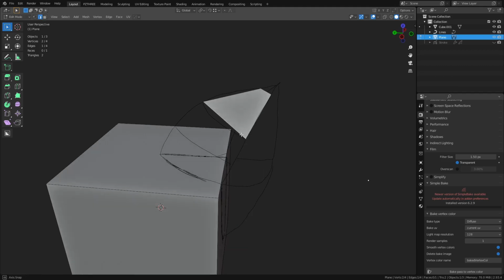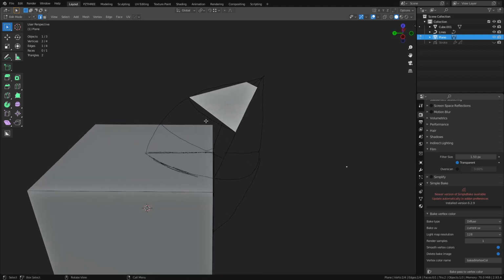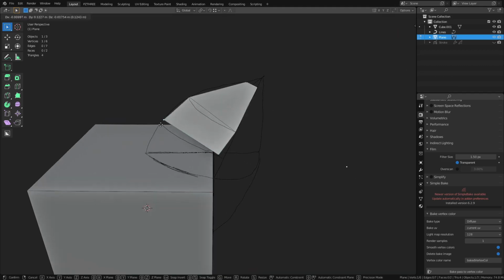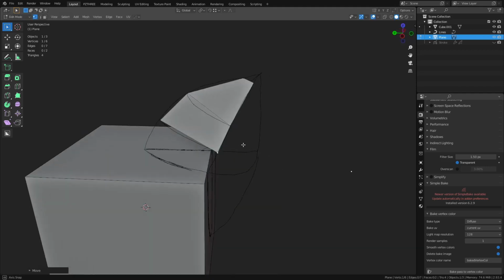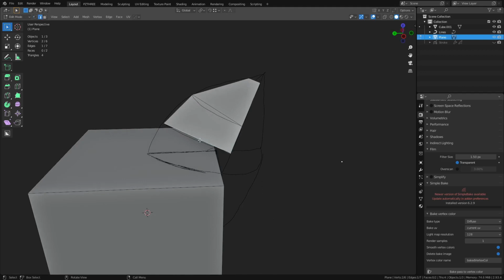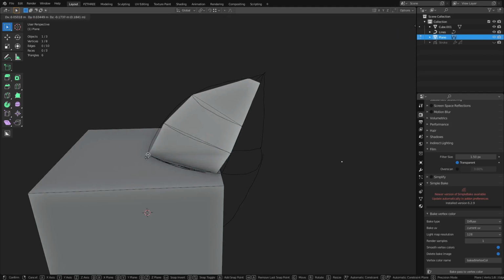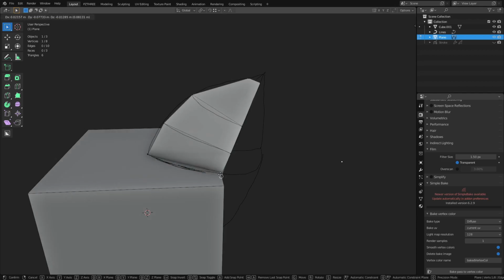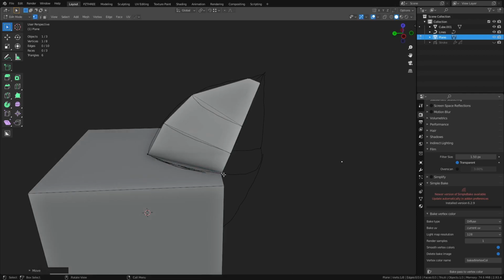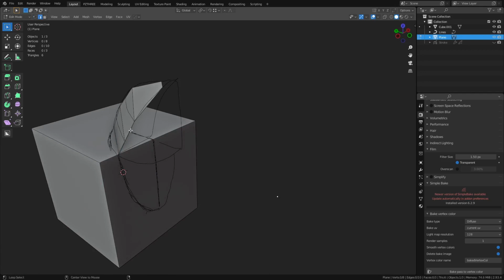That's just a conflict between Machine Tools and Blender sometimes. It happens. Not real sure why though. Maybe it's something else I press. So now we can take this edge and just press E, extrude it, grab the point, hold Control, hit Alt Z to grab that one real quick, and snap it right here to this corner. And we can work around the other way now.